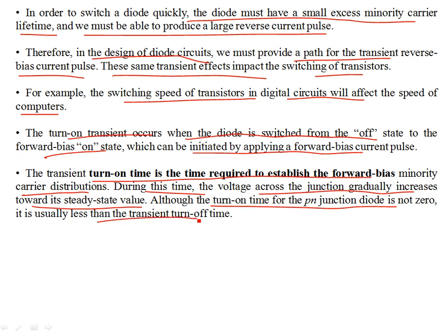The idea is because of the settling time of the charge. You can think of it as the settling time of minority charge carriers, or the minority carrier lifetime. There is a certain storage time or settling time which is required for the transistor or the diode to switch from one state to another. Because of that, the switching does not happen instantaneously. You must remember this. This is due to the basic capacitor action.